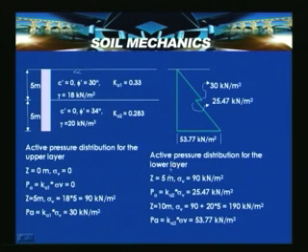One at Z is equal to 5 meters, but just below this line, which is governed by Ka2, that is phi dash is equal to 34 degrees, Ka2 is equal to 0.283. This yields Ka2 into sigma V, the same vertical stress but with different soil properties. With that, the ordinate we computed at Z is equal to 5 meters, just below this line, is 25.47 kN/m square.